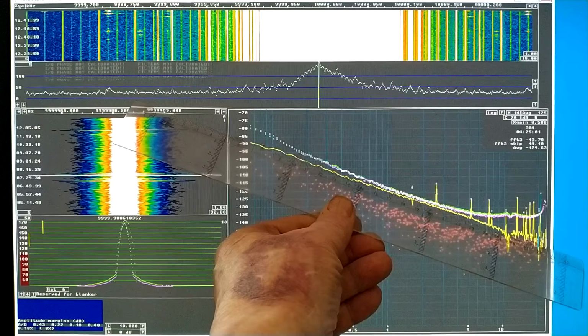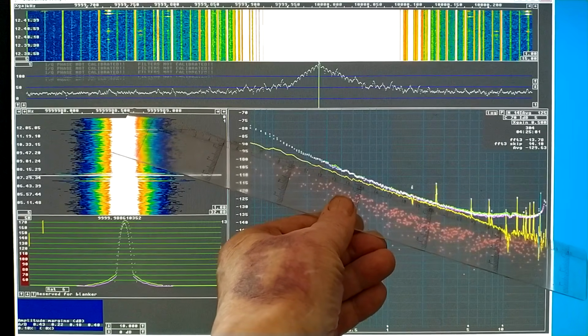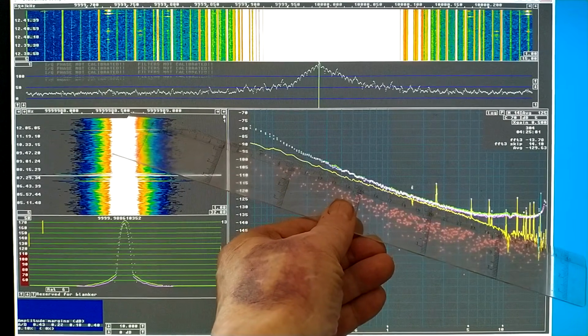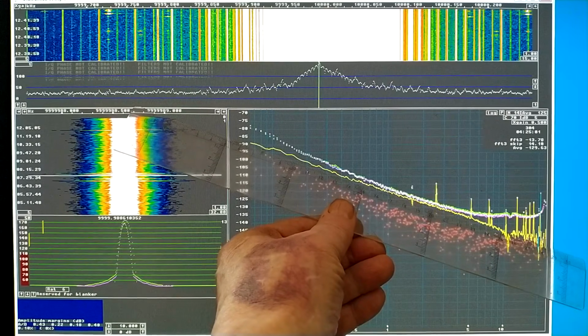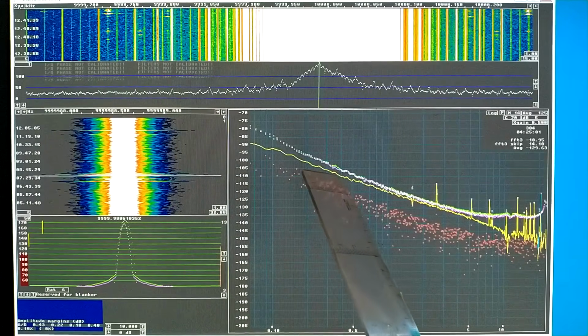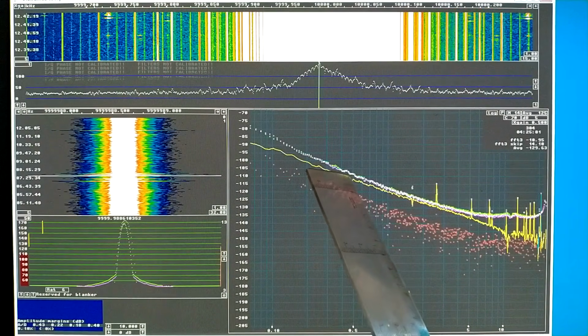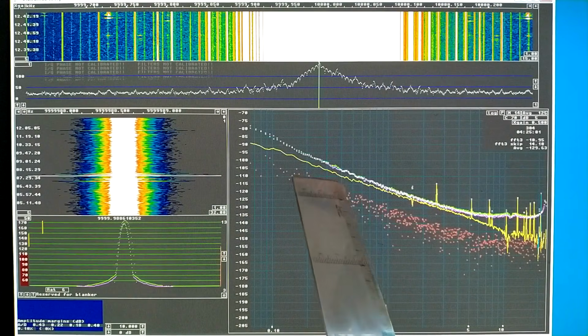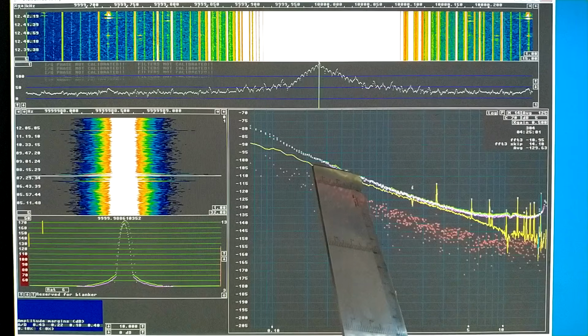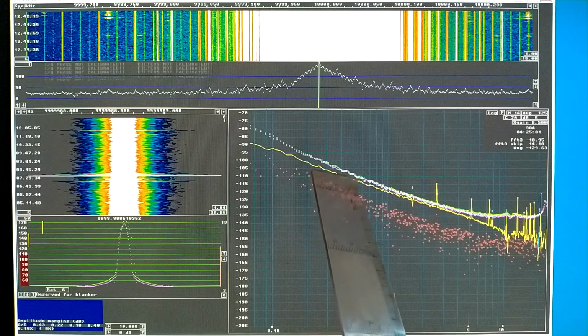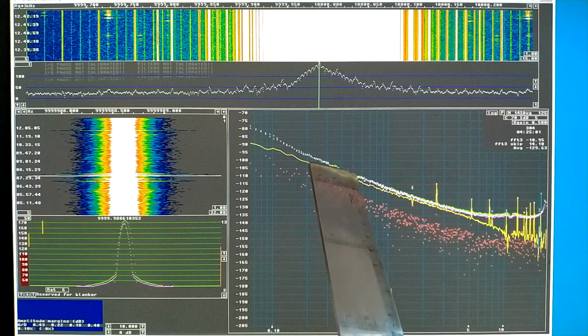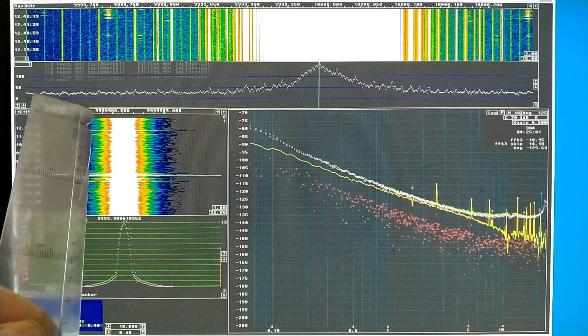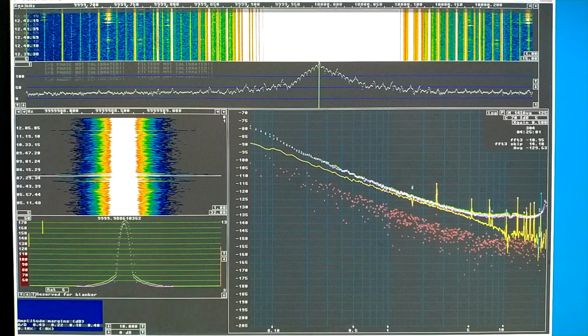You can see here the phase noise of the Wenzel oscillator looks perfectly like a straight line now. The bending that started here somewhere has disappeared. It was caused by correlated noise on the two reference oscillators. Now with the 100 times larger time constant, the place where this happens is moved down to very close to the carrier and not important anymore.